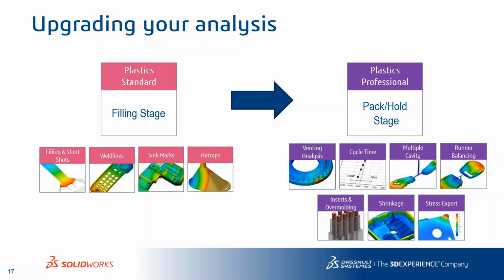And most importantly, a more accurate cycle time, because your entire cycle time goes throughout your filling stage, and it also includes how much time it takes to pack and hold the plastic part so that it completely solidifies before ejection. So this will give you a more precise cycle time, perhaps for quoting purposes, or if you are on a short deadline like you did for this example.